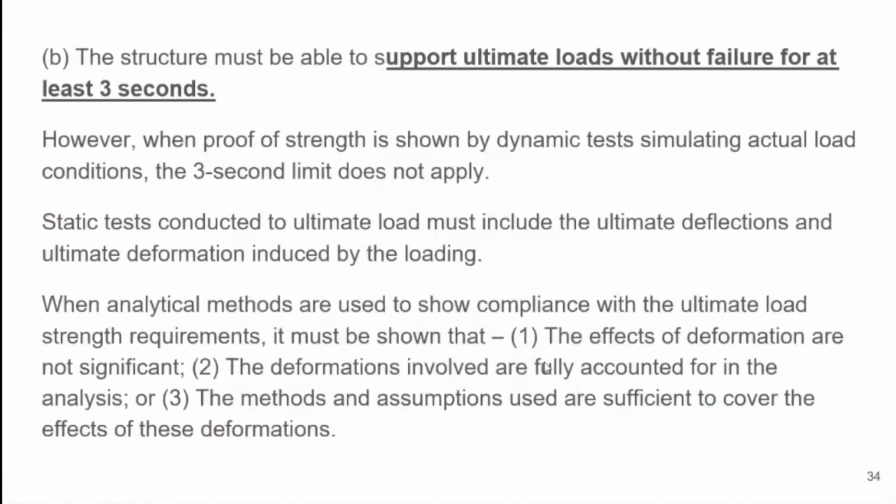So another thing is here, the next one is support ultimate load without failure for at least 3 seconds. So how do we do that? That's why the test is important, and this is normally the best and the easiest way to do it. You do the static test, you go to ultimate load, you hold it for 3 seconds. If the structure does not break, it is satisfied. If the structure breaks, not satisfied. That's why you look at a lot of videos on structure tests. They are testing up to the ultimate load and continue testing it until they break it.